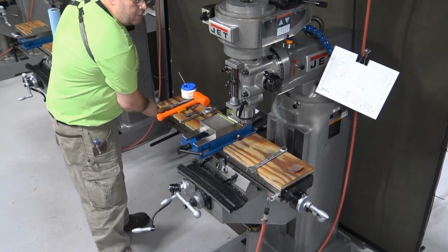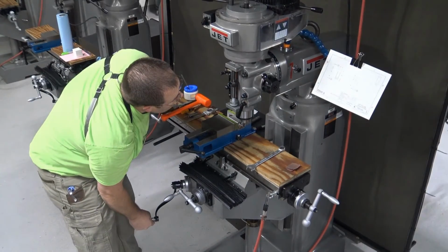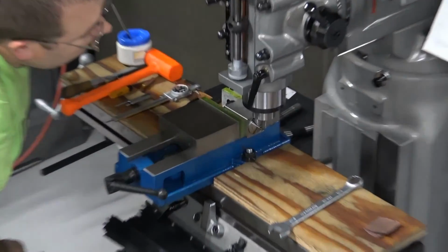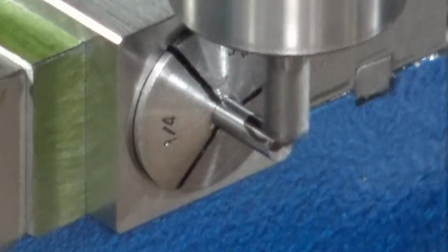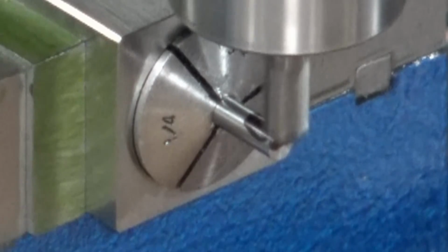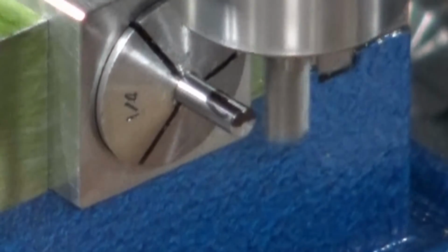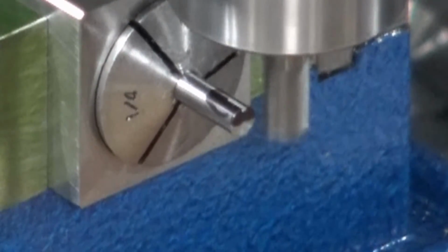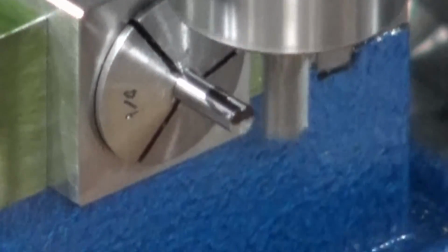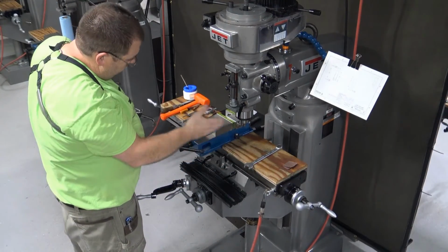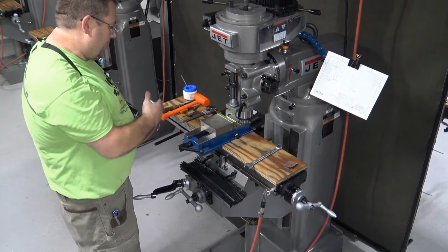So I've got my 0 set over here. I'm going to come up over the top surface of the part. I'm going to bring my knee down, or up, excuse me, till it just touches that top surface. There it's touched. I'm going to feed back. So now I'm going to set my knee hand dial to 0. Remember, we said that we're going to cut 30 thousandths deep, 600 thousandths back. That'd be one pass. Another 30 thousandths deep, 600 thousandths back.